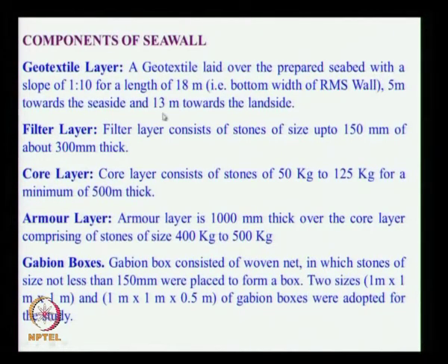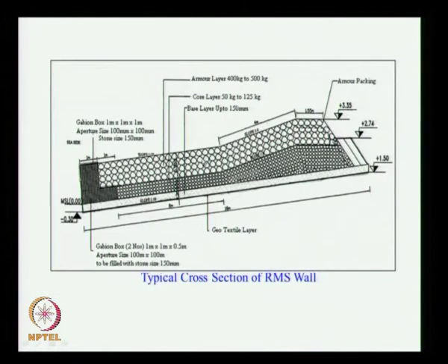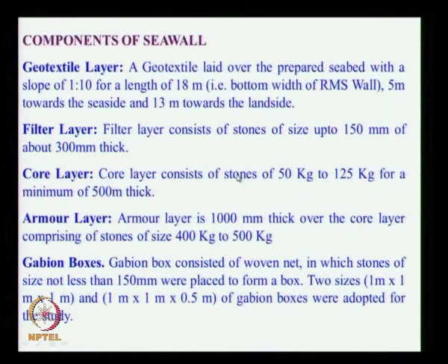The 5 meters towards the sea side is from the high tide level to the toe. The filter layer consists of stones up to 150 mm, about 300 mm thick. I said this base layer or filter layer can be sand, it can be stone also up to 150 mm size, because at this location the base material itself is sand.